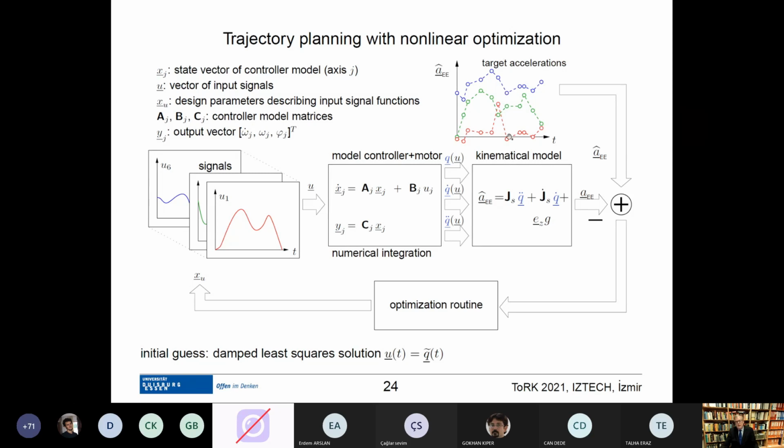And of course, the problem is that the robot might have moved already too far, so it cannot hold the acceleration anymore. So you have to really optimize the global motion of the robot so that at each position you can get as close as possible to the target acceleration. Because if you just accelerate, of course, then like in a roller coaster, the car will be 600 meters far away, and the robot cannot do that.